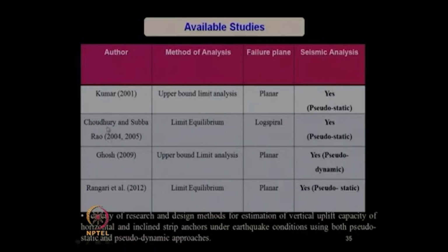Then myself, during my PhD I worked under the supervision of Professor K. Subbarao at IISc Bangalore. So, we had publications Chaudhary and Subbarao 2004 and 2005. The 2004 one is in the journal Geotechnical and Geological Engineering of Springer, and 2005 is in the Canadian Geotechnical Journal. We used the limit equilibrium method, one for horizontal strip anchor, another for inclined strip anchor. We used the log spiral failure surface, and for seismic forces we used the pseudostatic concept.